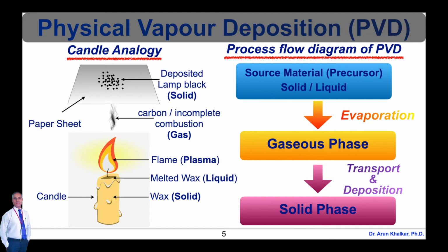In this process, the material that is going to be deposited onto a surface starts out in the solid form, gets broken down to the atomic level and transported in the gas phase, and afterwards becomes a solid again. The atoms of the deposition material will react with the gas during the transport stage. Any type of inorganic and a small range of organic materials can be applied via the physical vapor deposition method.